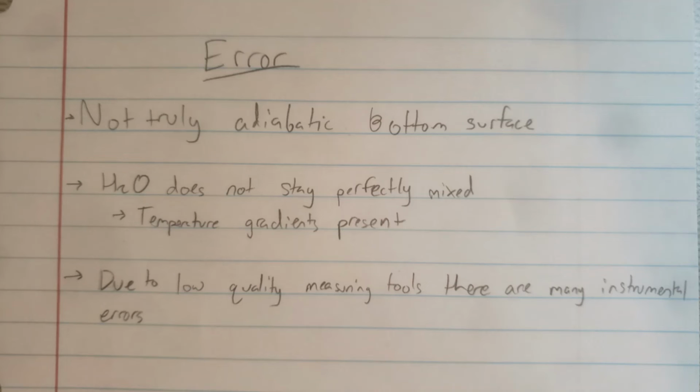However, when we calculate the Biot number, we find that the numbers work out such that with a 1 millimeter thick layer of water and a conduction coefficient of 0.606 for water, any convection coefficient less than 60.6 will result in a Biot number less than 0.1, so we are able to assume there are no temperature gradients present.